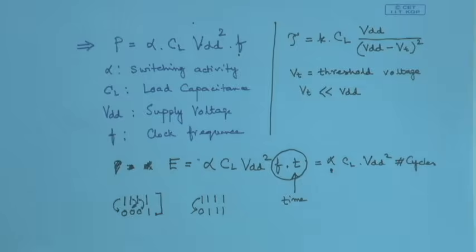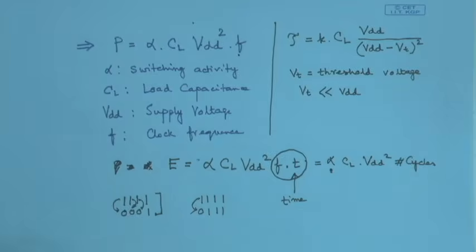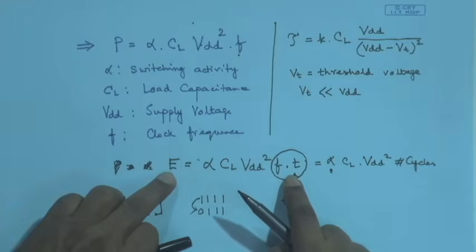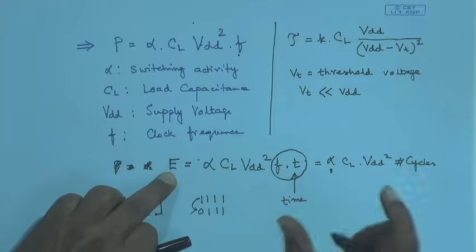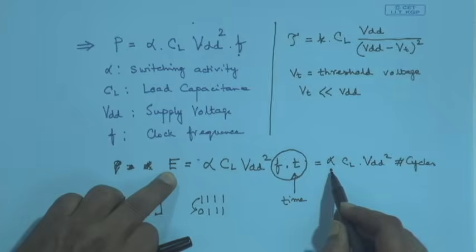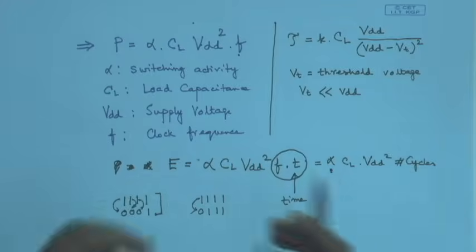But over a large segment of code, you can probably try to make some estimates. A number of interesting issues are coming out here. How can I save energy under a given timing constraint? I have to take some time. We can reduce VDD, reduce the switching activity, reduce the CL, or reduce the number of cycles. If I take fewer cycles, thereby we can gain.